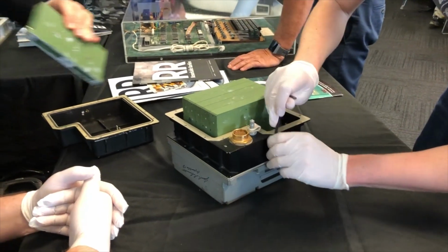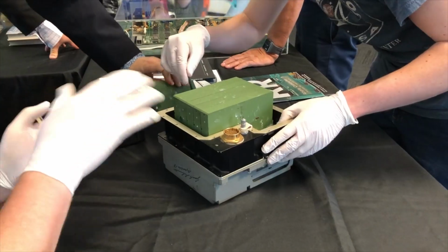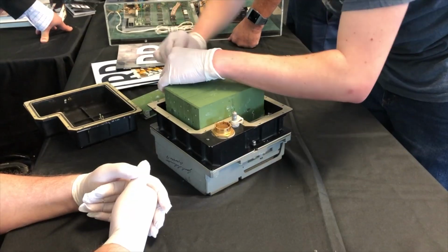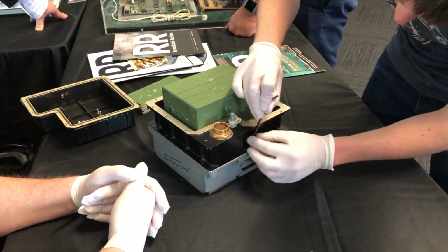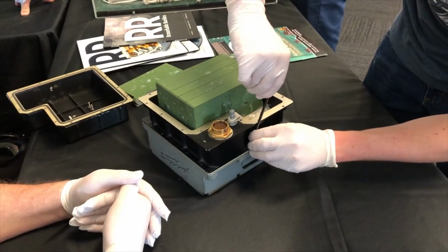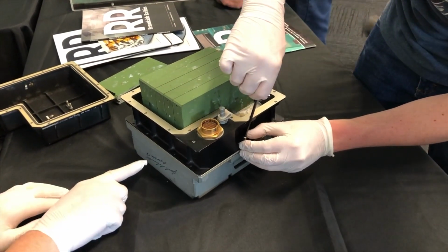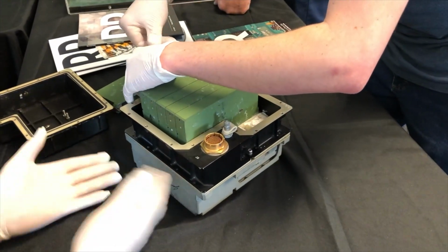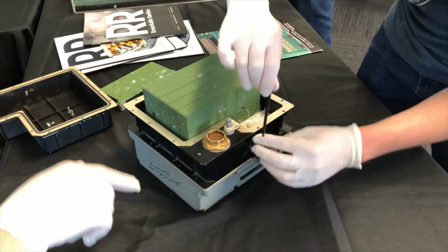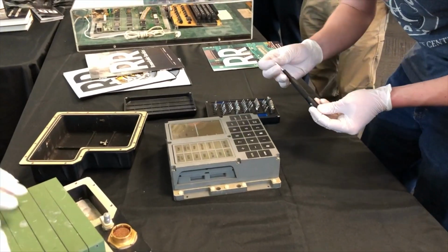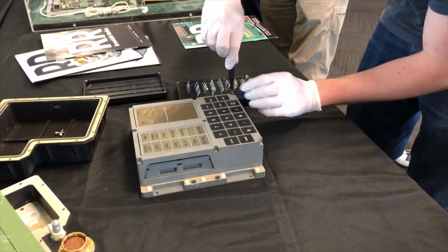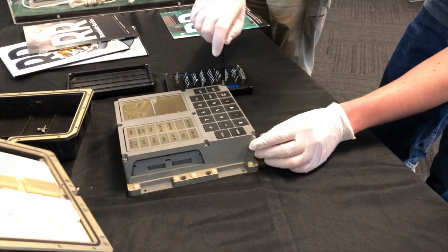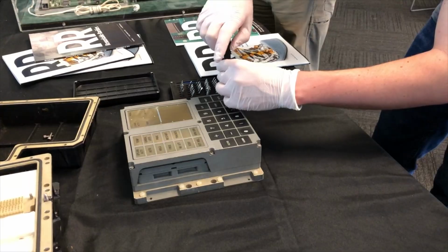So Mike is already furiously hacking at it and has removed the black back shell. You can see it on the table and spot the hermetic seal that runs all around the edge. That gave access to the green blocks, which are stand-ins for the actual electronic modules. These are not functional, they only contain a resistive element to generate heat. In this way, they could do thermal testing of the Block 2 DSKY design. Mike is starting the disassembly of the front part of the DSKY. It appears to be made of functional parts, a full keyboard, the warning indicator panel, and our famous electroluminescent display panel.